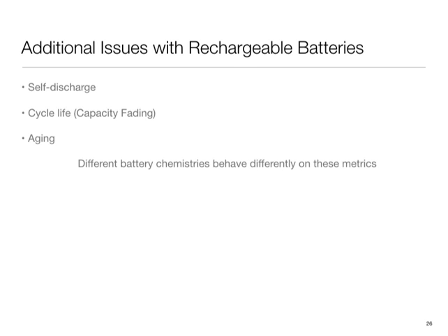Cycle life, or capacity fading. Every time I discharge the battery, next time around, that CP term is a little bit lower, and a little lower again. And ultimately, when it hits low enough, currently the number seems to be that when CP lowers by 20%, so you have lost your peak and your capacity is now 80% of what it used to be, then we declare the battery dead, or use whatever metrics like that. So I guess the target for a manufacturer like Apple, given their 2-year warranty or whatever, is that your battery would hit the 80% point no earlier than that period.